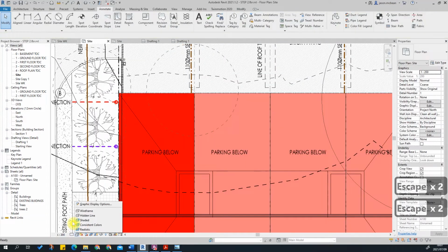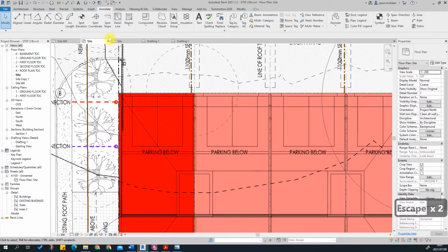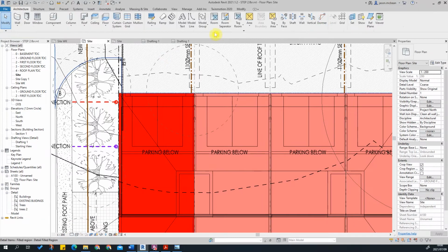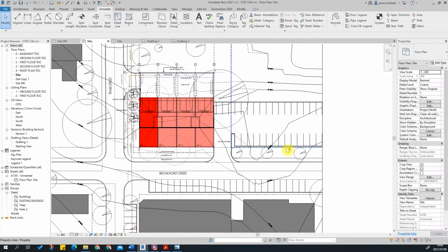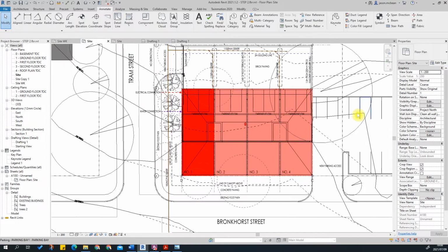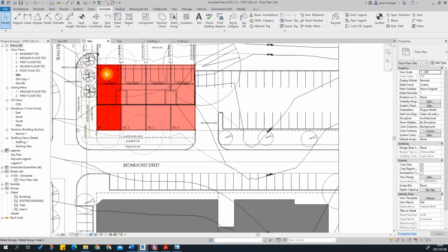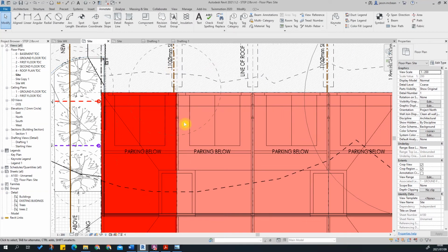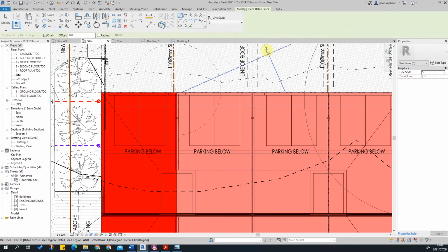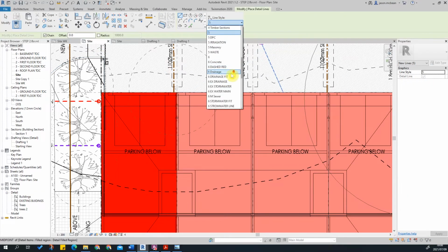Okay, great. I just need to introduce the parking in the basement. I can use my wireframe mode. Wireframe, you can see into the basement architecture. So here I'm just going to use annotation. I'm just going to use a basic drafting line in this instance, because you also need to go and number all the parking. So you need to go and number the bays that are in use. So I might use these 4 bays, and I might pick another 3 or 4 bays here as visiting parking. Okay, but for now, all I need to do is just go to detail lines and just say hidden.